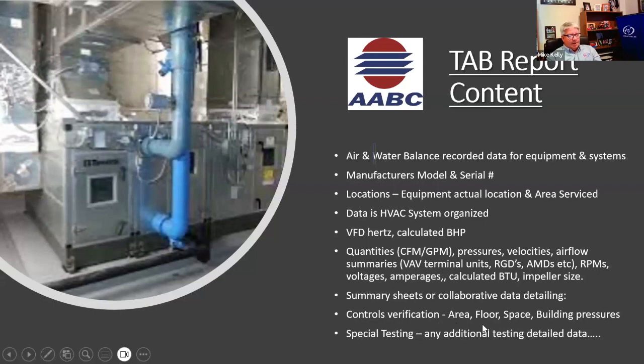Controls verification: area, floor, space pressure, building pressures. Controls verification is a new thing that AABC has adopted in the past 10 to 15 years. It should be listed in most testing and balancing reports if it's called out in the specifications. It's not something you get for free by just specifying air balancing. It should be called out to say per AABC standards, controls verification should be applied. There's a specification and a standard for that in the AABC. And then of course, any special testing, any additional testing detail.